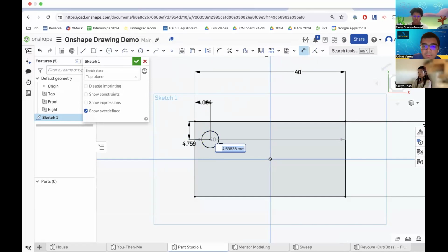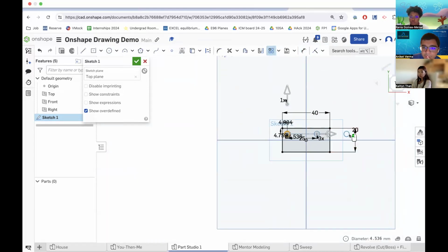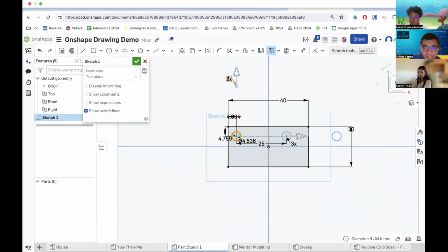And then how I basically use linear pattern is I have this tool right here, right? This one with the 4 squares. I hit linear pattern. It's going to prompt me for a couple things. It's going to show 1x in the y direction, which basically means that in this particular instance, the default is that linear pattern only has one instance in the y direction. So all of your instances will be in the x direction. As you can see, there's 3 of them, 1, 2, 3.